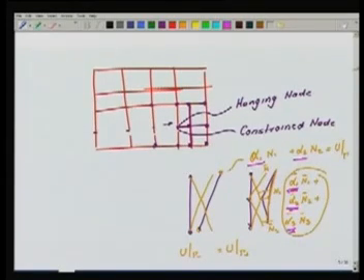What is the advantage of it? Let's say I have a crack here or a singular vertex here. Then I can zoom in the approximation towards this without propagating this refined meshing elsewhere. So the cost of computation goes down. It's much more economical because I know here the solution is unsmooth, so I'll have to take care of it locally. So I keep on doing this kind of local refinement to capture that unsmooth behavior, and I'm done, while the mesh elsewhere remains continuous.